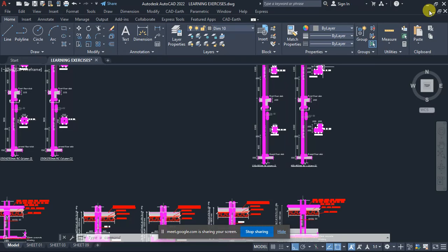Now in most cases, I pick the loads from Prota. You can pick their actual loads and moments. And I use the same moments on the base, because these same moments from the column will affect the base.